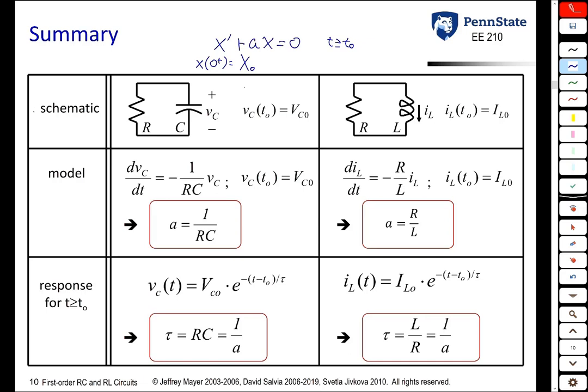In an RC circuit, for t greater than 0, you're always going to have a capacitor and some Thevenin equivalent resistance. In our example, it was a single resistor, but it doesn't have to be a single resistor, as we're going to see in some later examples. It could be resistors in parallel, in series, or any combination. But regardless of how many resistors you have present, you can always model it as a single parallel resistor to the capacitor.